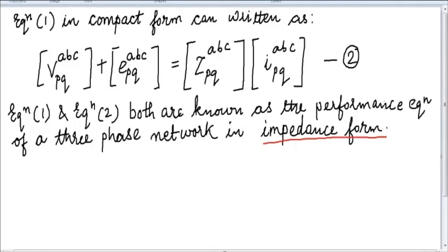So both the methods of the representation is widely used in the power system analysis, like the load flow analysis. That is, if we analyze the condition of various buses in a power system network by using load flow analysis, there we require Y bus, that is the admittance bus. So we have to first formulate the admittance bus and then we have to start with our necessary calculations.